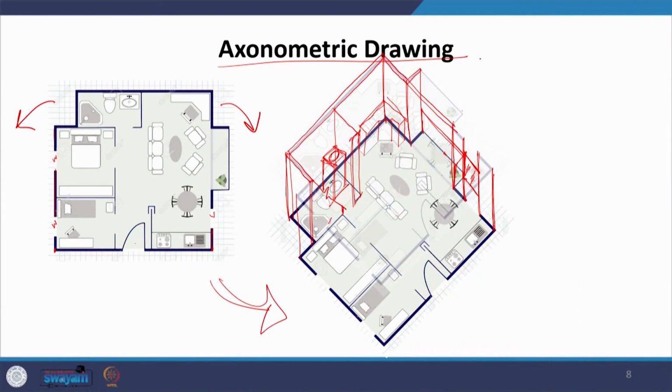So, I hope you understand the difference between the isometric drawing and this military drawing, which we are understanding as axonometric henceforth. All these are types of axonometric projections, but their usage varies slightly. For architectural purposes, for extruding the plans, for showing the plans in 3D and understanding the architectural drawings, axonometric drawing or military drawing is what we are going to be using.